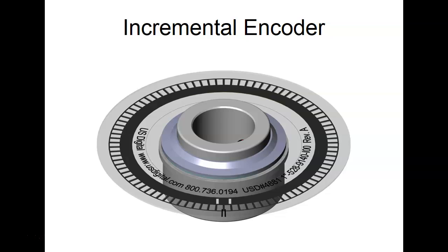Robots, we call it mastering. So you have to master the robot. So if you ever lose the contents of your encoders, then none of your programs will run because they don't know where it starts from. So this is one disadvantage of an incremental encoder: you have to start it from a known position. So we set zero somewhere.